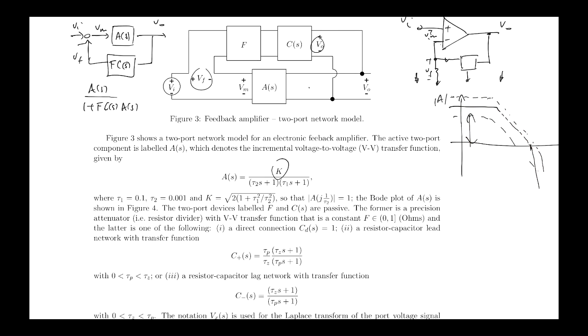That's the characteristic that you get when you build an op-amp, right? So inside an op-amp, there's a pair of transistors in a differential amplifier configuration, and there are resistors and capacitors in there to set bias points and so forth, and that leads to this sort of characteristic across frequency.